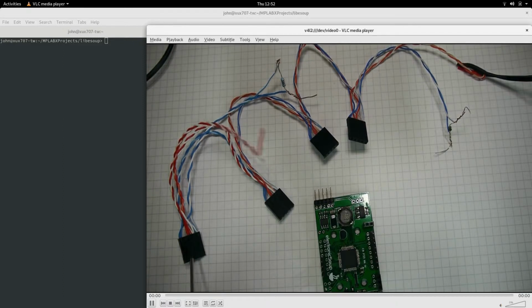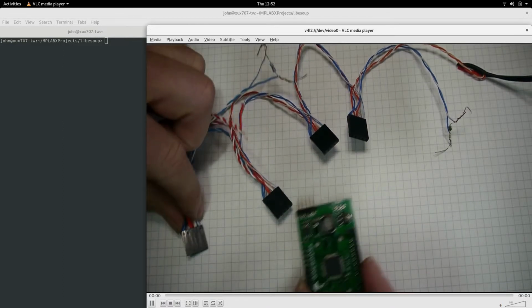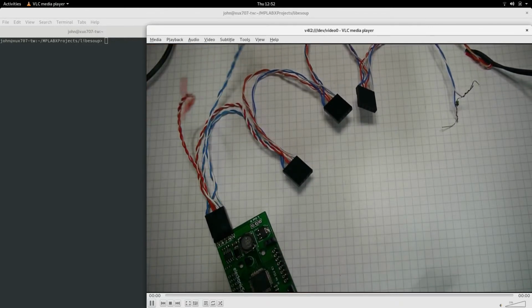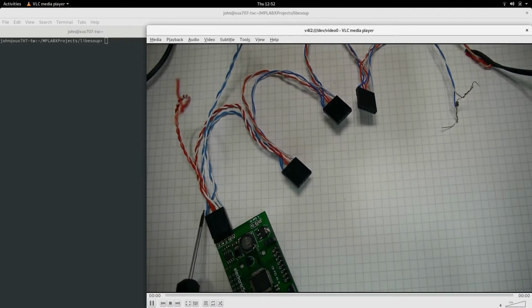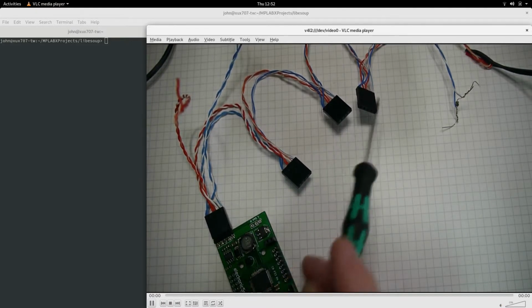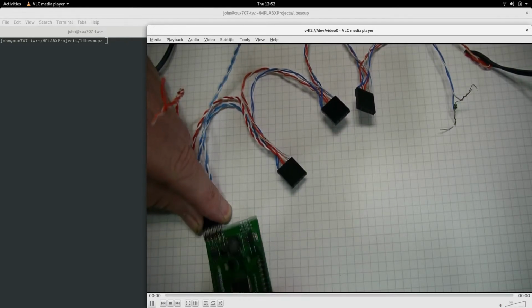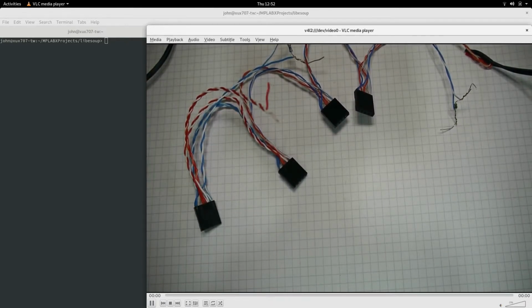Now, if I connect up my node here, I have to connect consistently. So if I'm connecting CAN high to the solid blue, then all nodes have to connect in the same orientation. Otherwise we're going to have problems on the bus. So CAN high, CAN low, differential pair.